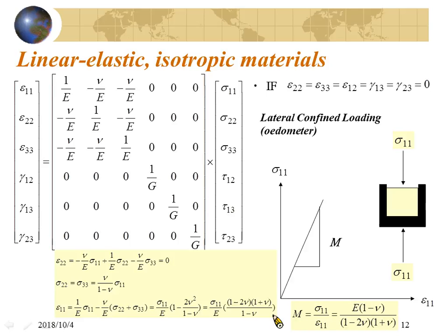So please derive this by yourself. I always like to ask a question about this when I teach soil mechanics. What do you think? Is M larger or is Young's modulus larger? Which one will be steeper?